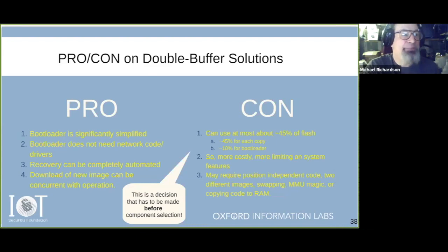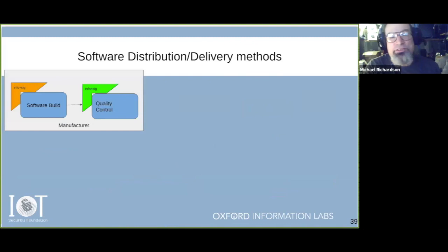So how does this happen? How does the whole process go on? Well, the scenario that I've experienced and envisioned in many places is the software workers and the developers do software builds and they compile and then they sign their image with a development key. The development key can be run by a bootloader. That's the orange signature there. It can be loaded by development machines, which happen to have the R&D key. So the R&D machines will run production code, but they'll also run developer code, and they test it. And when everything looks good, they hand it to quality control.